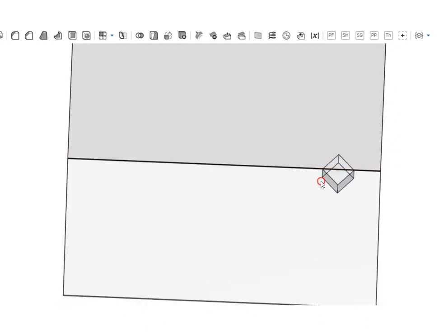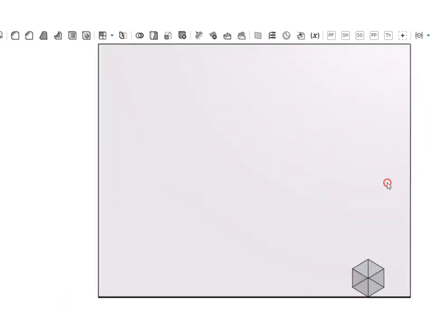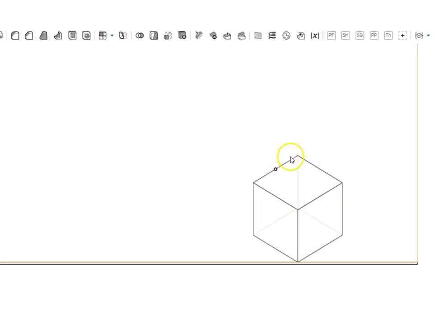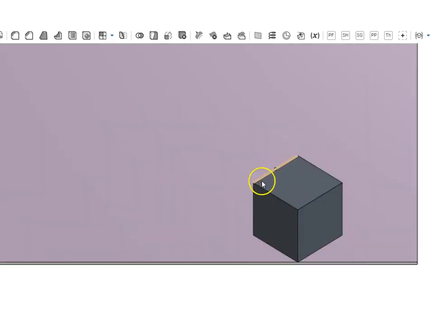So the interesting thing about this position is that if you look from the front view, what you actually see is an isometric view of this cube. When we learn about isometric, it will be clear to you that when a cube is positioned in this manner and projected in the front view, what you ultimately get is an isometric view. And to see it more clearly, let us make it into a solid view with the hidden edge visible, so that now it is much more clear to you. And so this is a typical isometric view where you could see all the three faces.